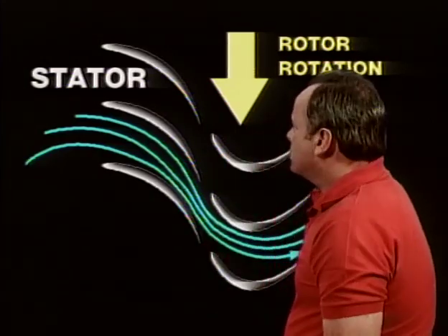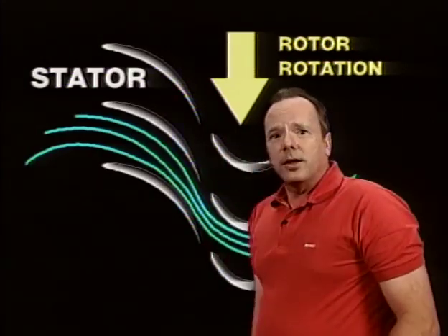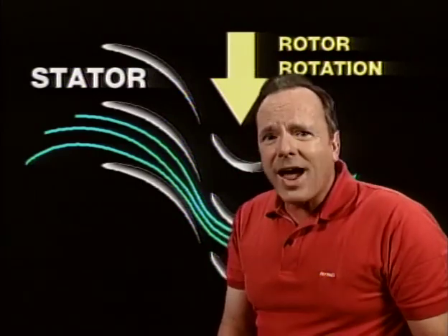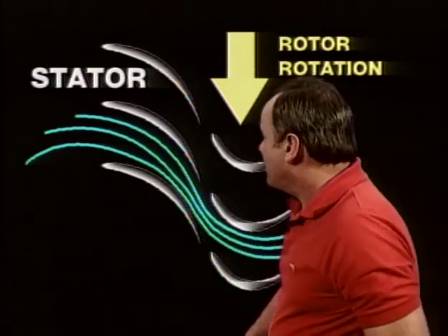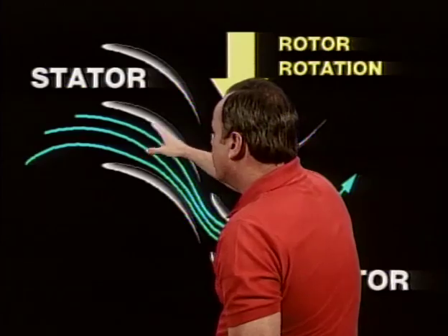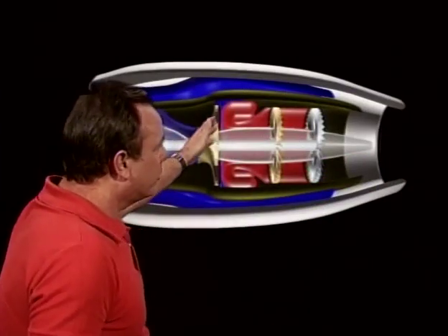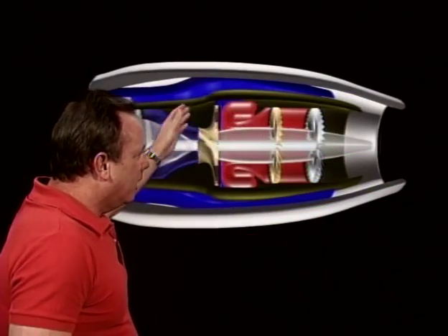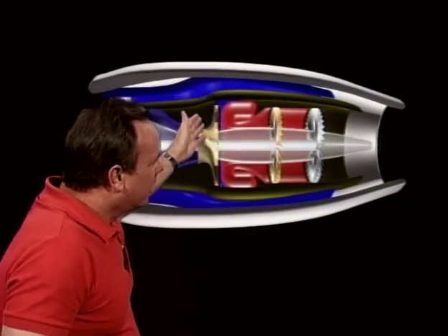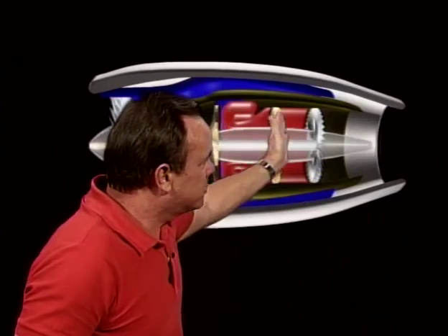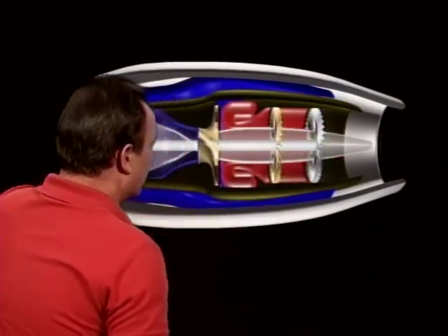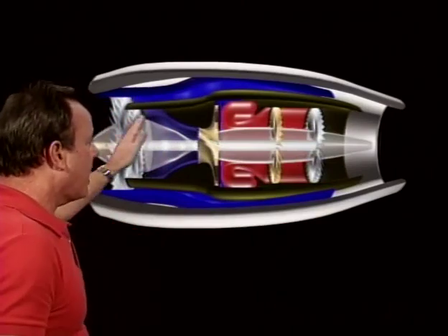The hot section of a turbine engine is particularly susceptible to what is known as cracking damage, and cracking damage will come because of a tremendous amount of heat. Of course, the hot section begins when you add fuel to the air in the burner can and you have flame going on, and that really hot air now goes past the turbine blades, and the turbine blades are in the hot section of the aircraft. Once again, the compressor blades up here, you're just compressing the ambient air.